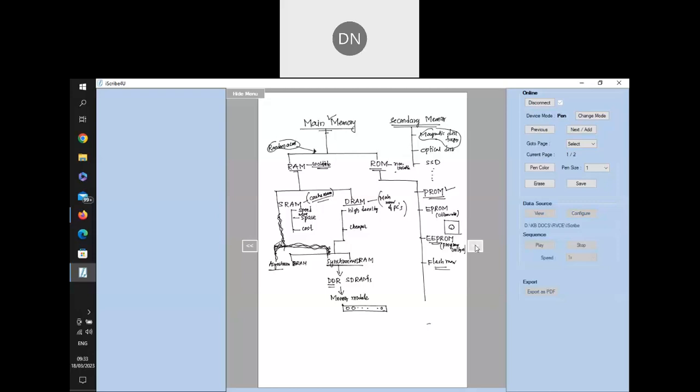But flash memory is more suitable because you don't require a separate programming voltage. A normal 3.3 volt supply is sufficient. So most of the ROM type memories currently used in the market are flash memories. If you take any microcontroller, let's say our LPC2148, which you are studying next semester, it has a read-only memory inside. What type of memory is used? They use 512 kilobytes of flash.